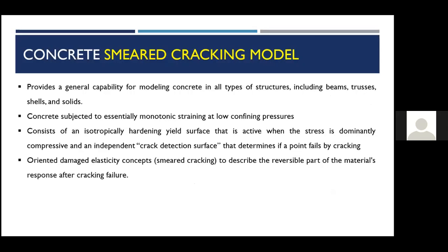Coming to the concrete smeared cracking model. This model is also used for modeling concrete of all types, like beams, trusses, shells, and solids. Unlike the damage plasticity model, here you can use it only for monotonic straining. You cannot use this model for cyclic loading.